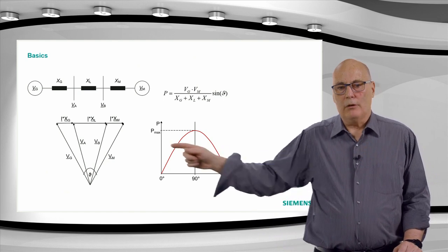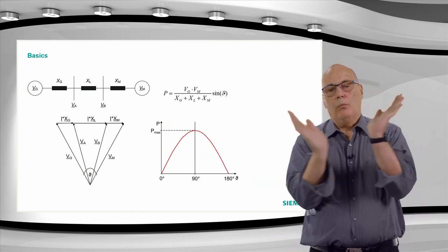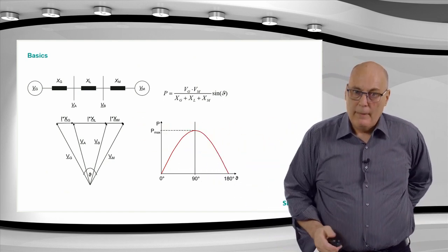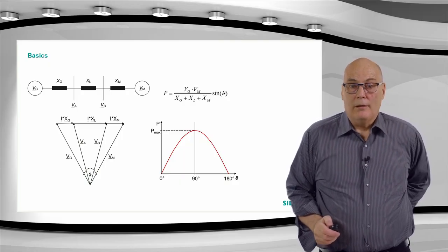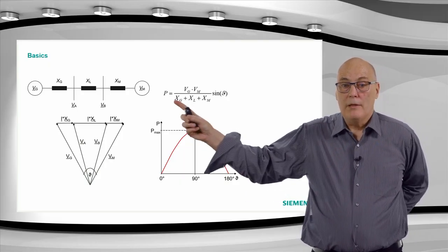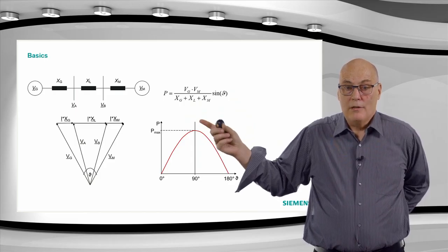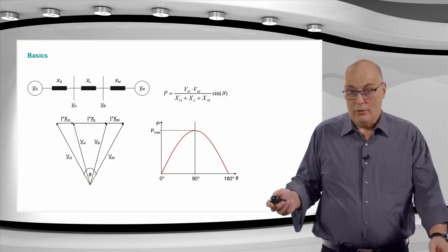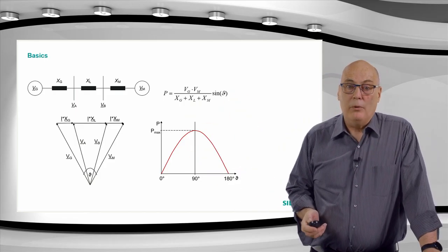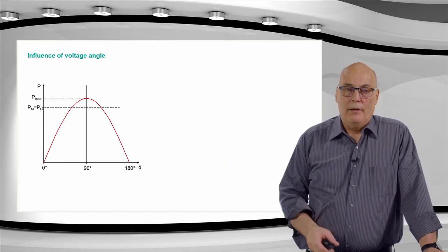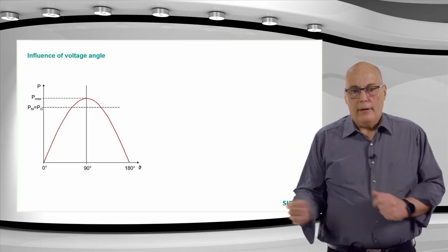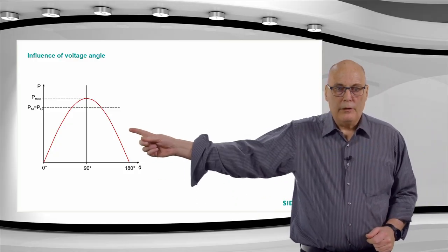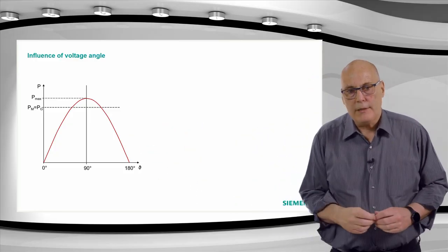Why does the power not get larger? Because if the angle gets larger, we go, as we'll see on the next diagram, into an area where the voltage starts decreasing very rapidly, and then the power gets smaller, because power is current times voltage. So simply increasing the current is not going to just keep increasing the power. At some point the voltage is going down, and then the power will go down again. So that diagram, now let's look here and we define some points.